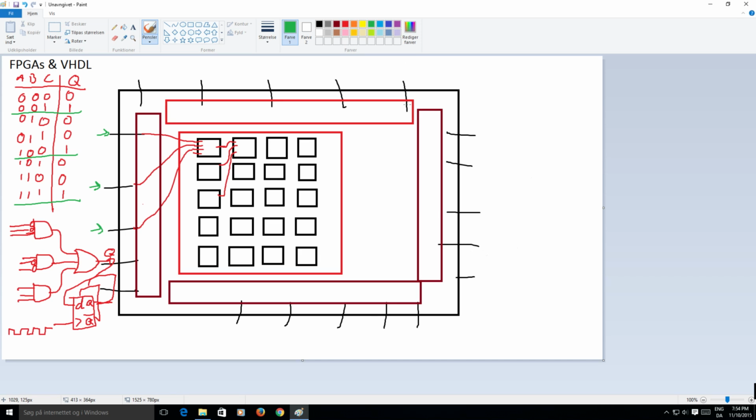I'm not sure if you can get 5 volt I/O for any FPGAs, but at least they can go up to 3.3 volts. So you can power one I/O block from 3.3 volts, for example, and then you can power another one from, say, 2.5 volts. So depending on what you need to connect to, you can use different voltages on different I/O blocks. You also need to be careful, of course, when you have different voltages, that you connect the right stuff to the right pins. So we could make this one 3.3 as well, and then we don't care about the last one.